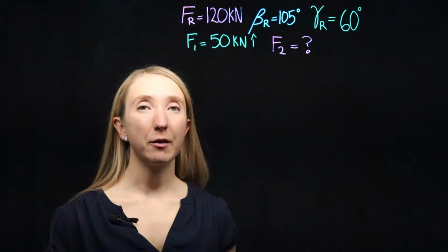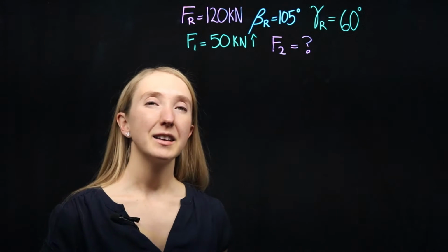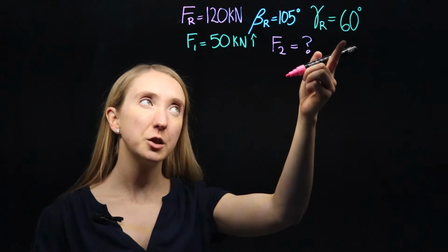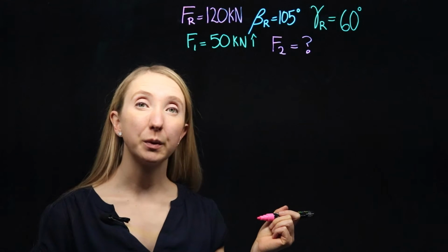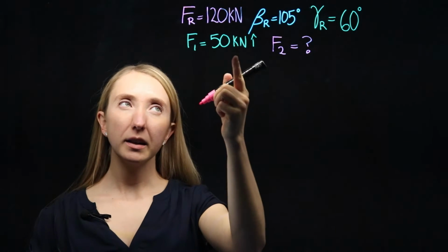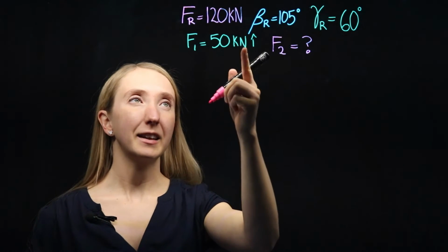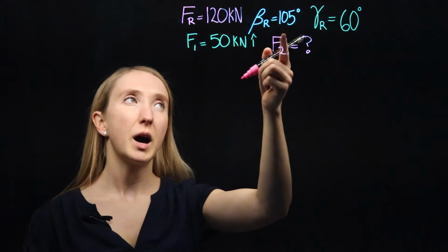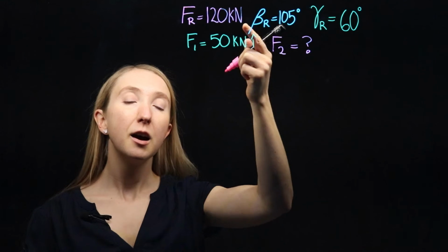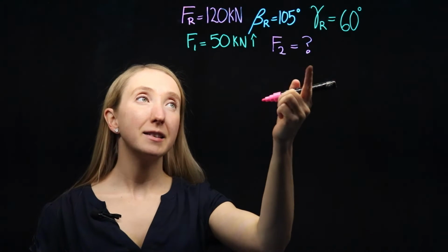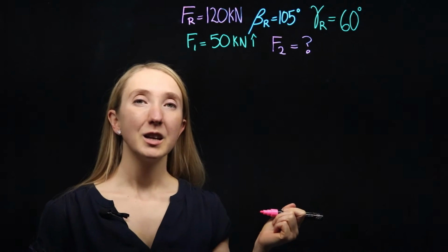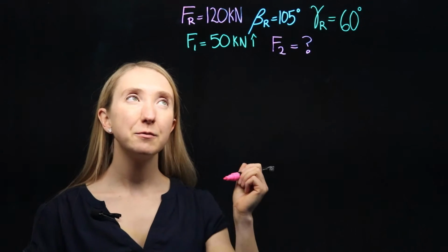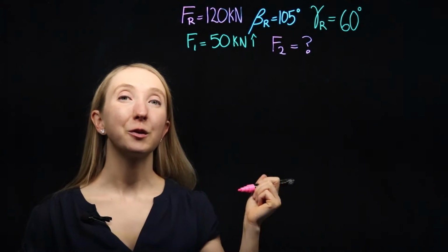Fr is equal to F1 plus F2. And we know that our Fr has force components in the y and z directions because of the angles we were given. But F1 only has a force component in the x direction. That means that whatever makes up the y and z components of Fr must be equal to our y and z components of F2. So we can solve for our F2 components directly by finding out what those components are for our resultant.